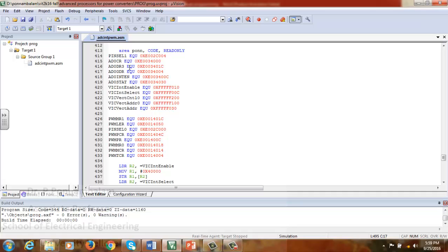In the NGX board they have connected channel 3 of AD0 to a potentiometer, so that's the reason I have chosen channel 3. We can choose whichever channel we want, and depending upon that we need to make hardware connections. As this NGX board gives importance to channel 3, I have used that one.